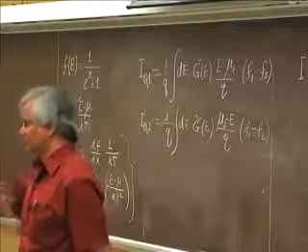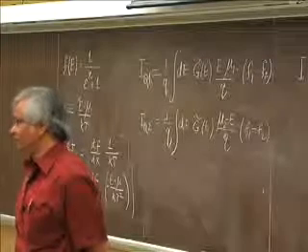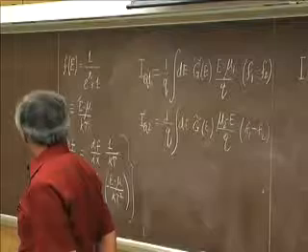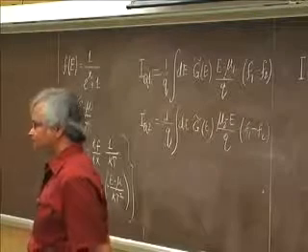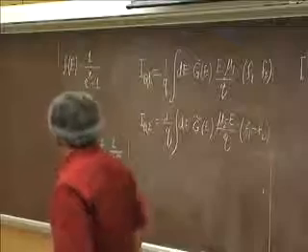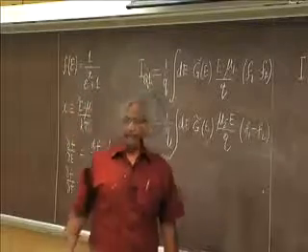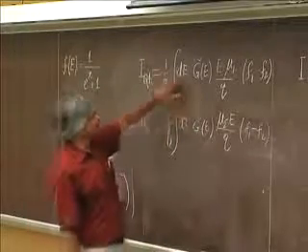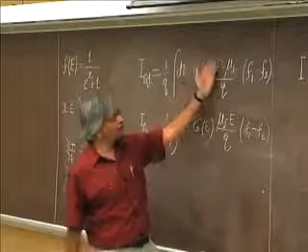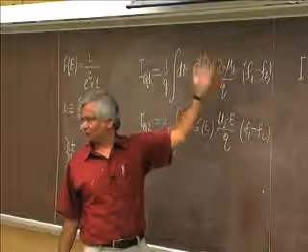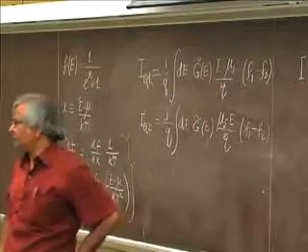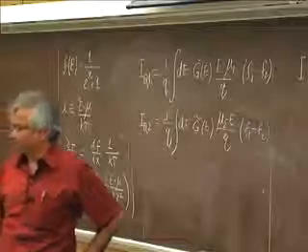But commercial devices are usually P-type materials and N-type materials in series. Because if it's very degenerate, then df/dE will be like a delta function. So if you replace E by EF or mu, it is 0. So finally, in order to get a non-zero coefficient, there has to be an asymmetry between E less than mu and E greater than mu. Otherwise, as long as it's all symmetric, you won't get any Seebeck or Peltier, any of that.